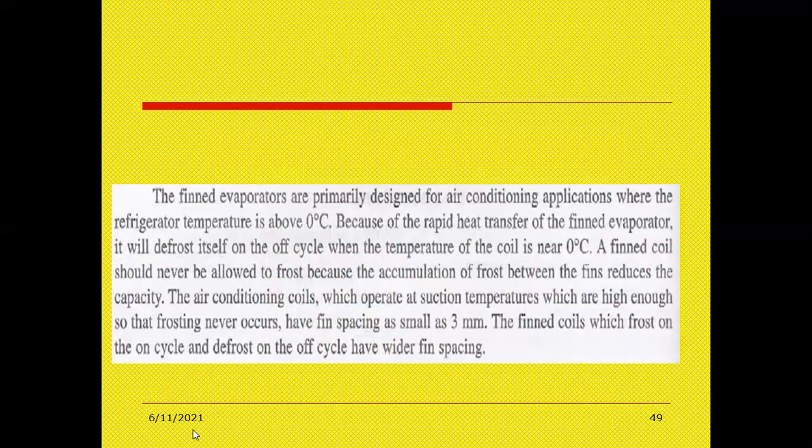The finned evaporators are primarily designed for air conditioning applications where the refrigerant temperature is about 0 degrees centigrade. So this type of finned evaporator is generally designed where the temperature is above 0 degrees centigrade, not considering minus degrees centigrade. Because of the rapid heat transfer of the finned evaporator, it will defrost itself on the off cycle when the temperature of the coil is near 0 degrees centigrade. A finned coil should never be allowed to frost because the accumulation of frost between the fins reduces the capacity. So here the space is reduced when it is frosted.